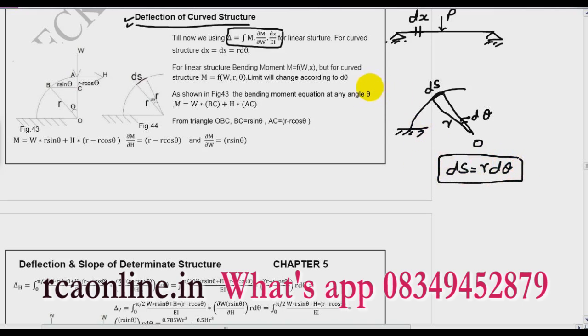So the first change which I will make in my deflection for Castigliano is that M into del M by del W, but in place of dx I will write r d theta. This is important. So what will I be requiring? Radius for this curved member. So r d theta over EI. First thing that you have to change.